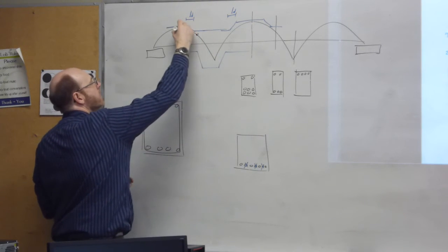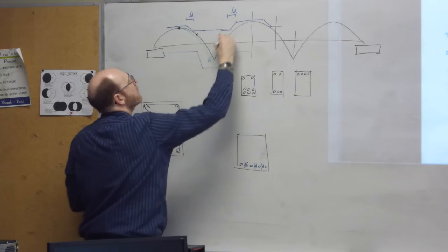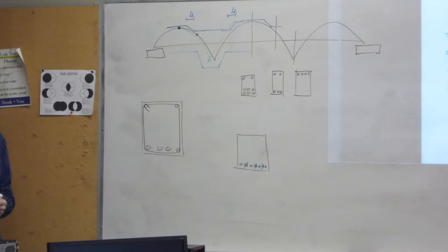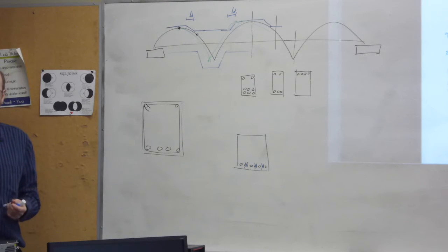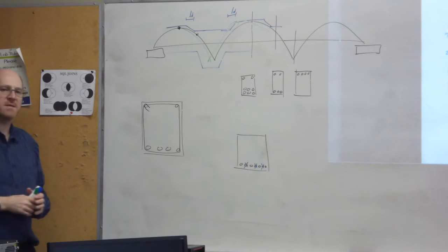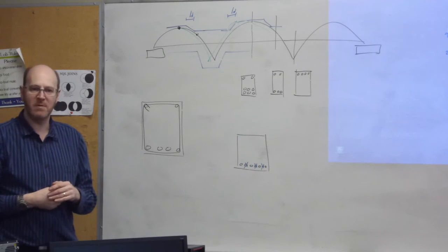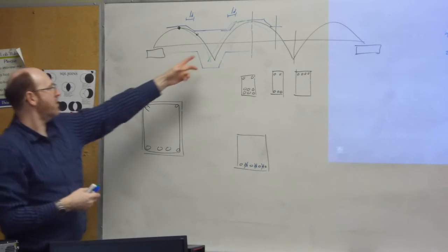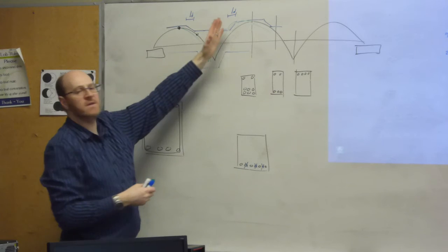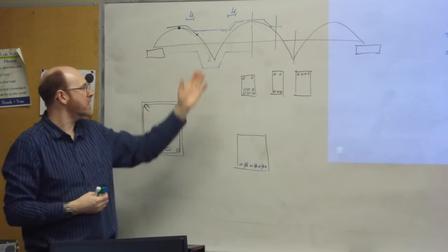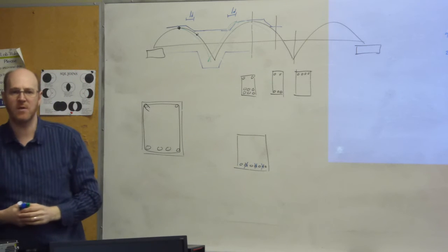load combinations is I could have a load combination that did something like that, and just in this little area it kind of pops out. So if you just check your maximum values only based on a particular load case or load combination, you might miss that on a load combination which does not cause a maximum effect, you do happen to have a scenario where the moment is shifted to one side a little bit, or at a different angle or something that causes you to be outside of that moment resistance curve.